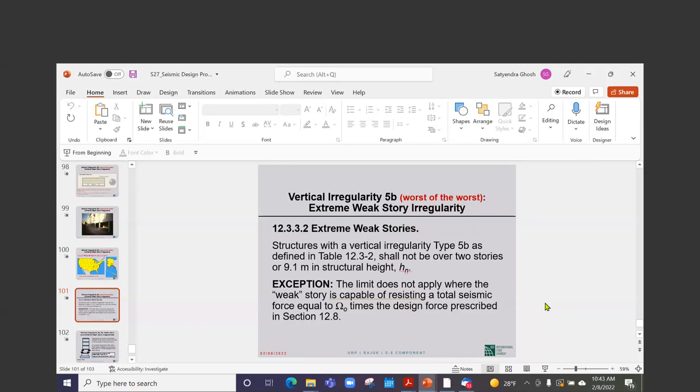If you use a rationally computed period, you are assuming a softer building, a building with less stiffness. If you ignore the limit of C sub u T sub a, you are further decreasing the stiffness of your building. If you decrease stiffness, you'll be calculating larger drifts, and the code has no problem with it. You are shooting yourself in the foot.